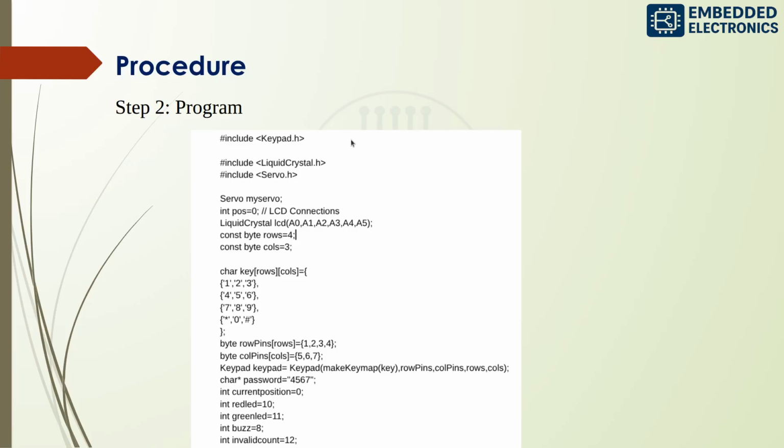First step is pin declaration. Here you can see the LCD pin declaration. All the pins are connected to the analog input. This is a clever way to save the digital pins. Just ensure the wires in the Tinkercad match those specific pins.